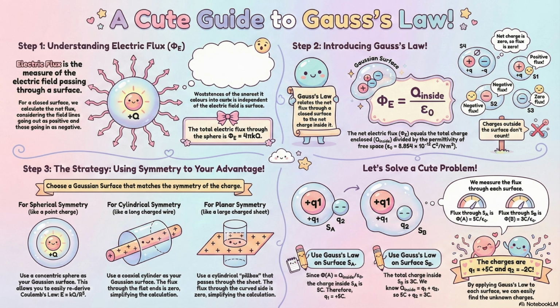And what about ESL? That's the inductance. ESL is even more insidious. It comes from the physical leads and the internal geometry. And at a certain frequency, that inductance just takes over. It does. At what's called the self-resonant frequency, the component stops acting like a capacitor entirely and starts behaving like an inductor. If you're designing for high-speed signals, ignoring ESL means your component might be worse than useless right when you need it most.